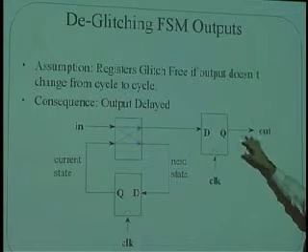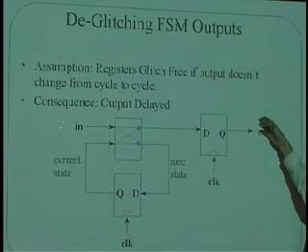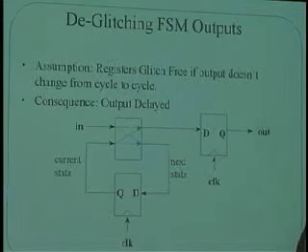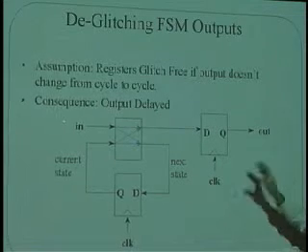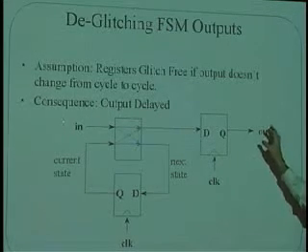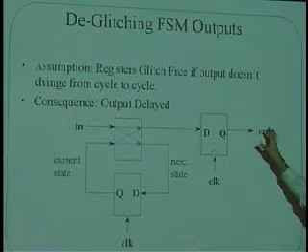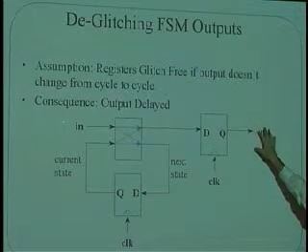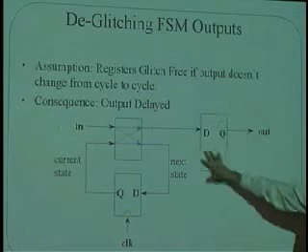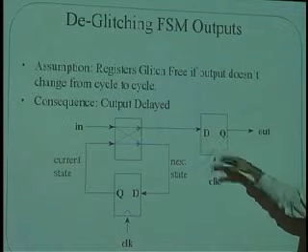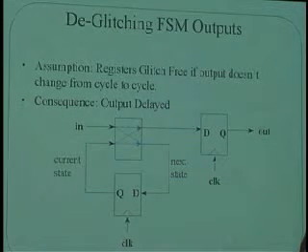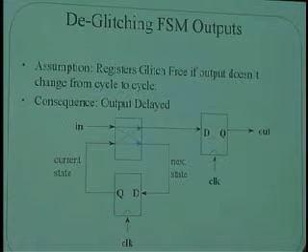It's only when it's changing from one value to the other that it goes through this intermediate time where the picture is developing on the output that we actually see trash there. And so this kind of a circuit here can actually de-glitch the output and ensure that it doesn't drop a code by accident. Okay? And that's used inside of these machines all of the time.